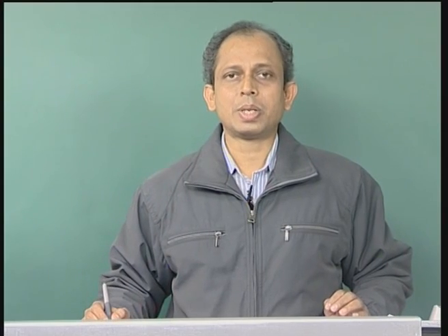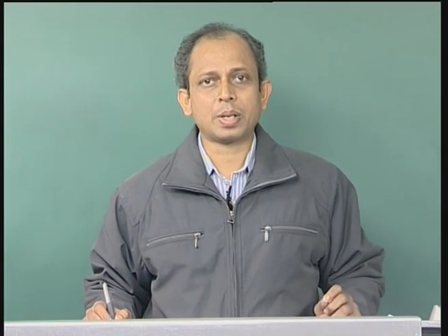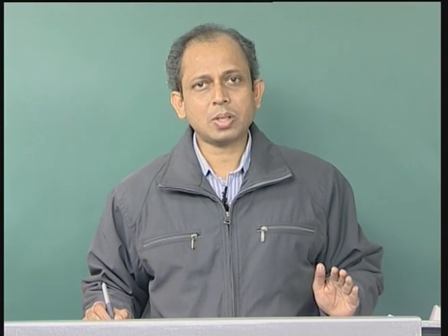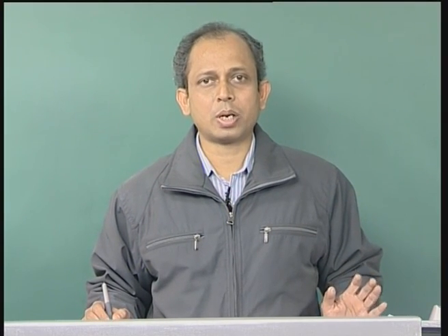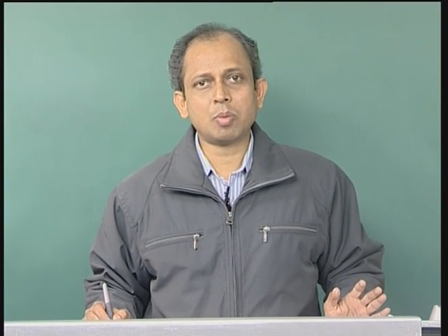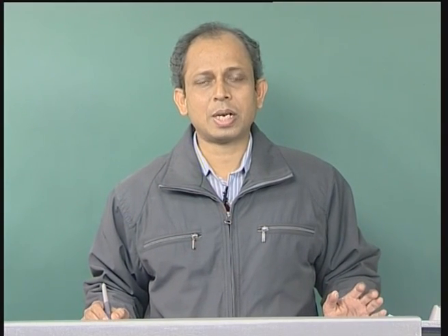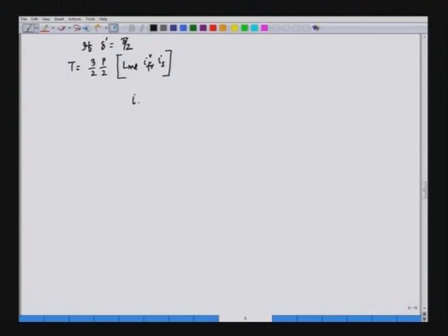So, in general we can say that IAS has got two components. It has a component along the field axis, that is called the flux component of current, and there is another component which is orthogonal to the field axis, that is in the Q axis, that is called the torque component of current. So, in general Is, if it is a phasor, will have If along the field axis or the D axis, and another component along the Q axis, that is called It.